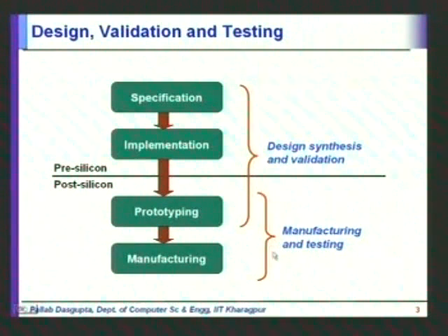And then what does actual testing do? The testing is not to find out whether the design is correct. Rather, when we actually translate a valid design into the circuit, there is a possibility that the circuit, because of the manufacturing process, may have defects, right?